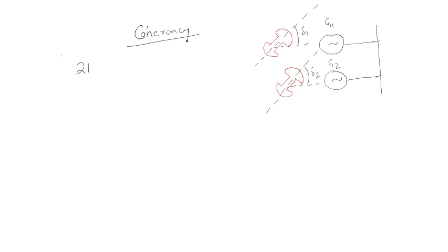So we have derived our swing equation as 2H upon omega s d square delta upon dt square equals Pa. Pa is the accelerating power, and that is our Ps minus Pe. Now here, these two machines, G1 and G2, are your two generators, and they are connected to the same bus. One bus system. This is your bus bar.